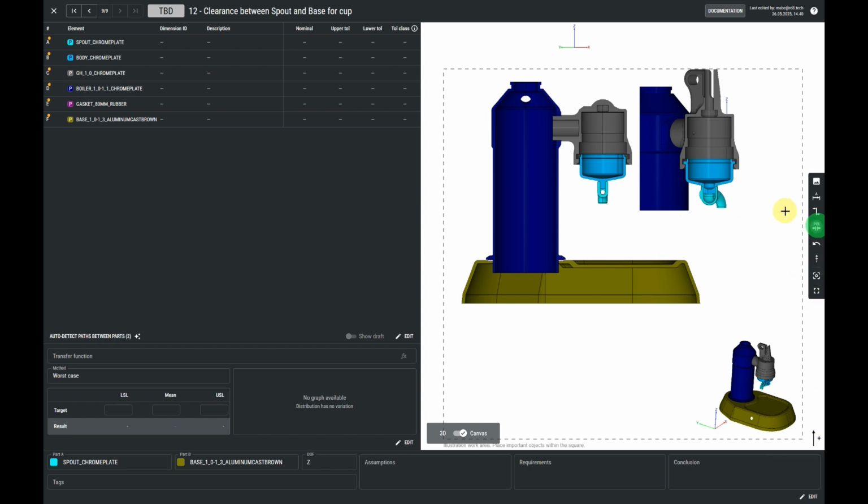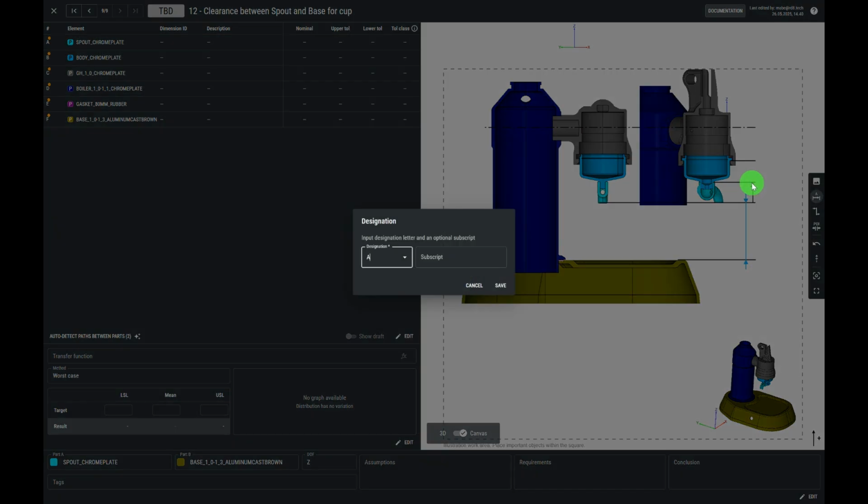I will adjust the direction to be vertical in this case, and voila, I now get nice aligned lines in my representation. To keep a clean illustration, I use the help lines to avoid having annotations on top of my geometry pictures. Now, I simply connect my arrows. Notice that they are automatically associated to my parameters.